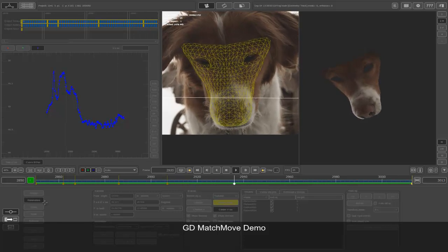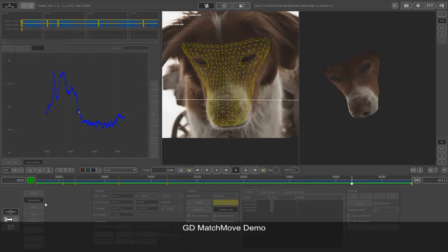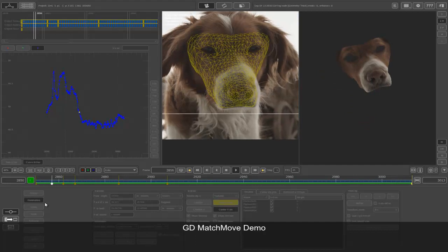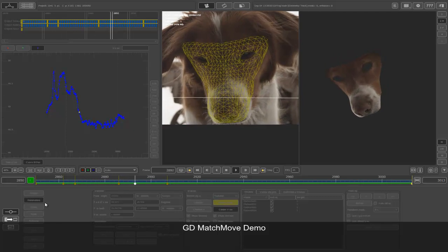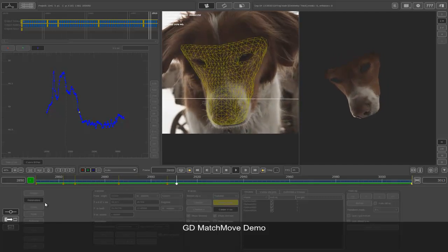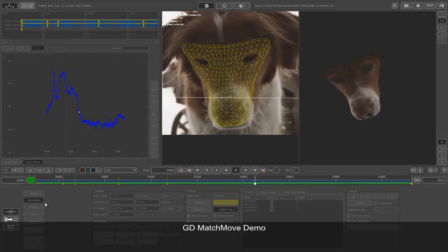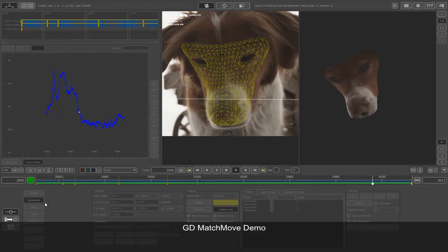So just make sure there is nothing slipping, there is no sudden movement in Z, and over here I also have the curve open for Z. As you can see, it really looks a lot jagged and really weird, but the point is the curve is moving only from a minimum value of 0.485 to 49.5, so it's only a matter of 1.5 centimeters, so it really doesn't matter a lot, and it doesn't really move a lot suddenly. It only moves a lot when there is a sudden rotation, like you can see these two peaks over here, and these small regions are so small that it's in millimeters and you really can't make out, and thus absolutely no problem.